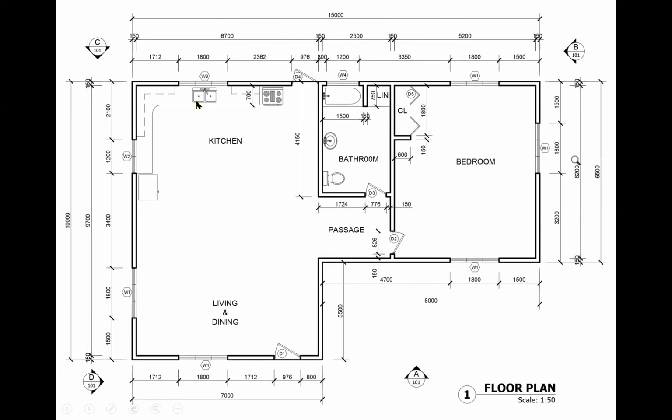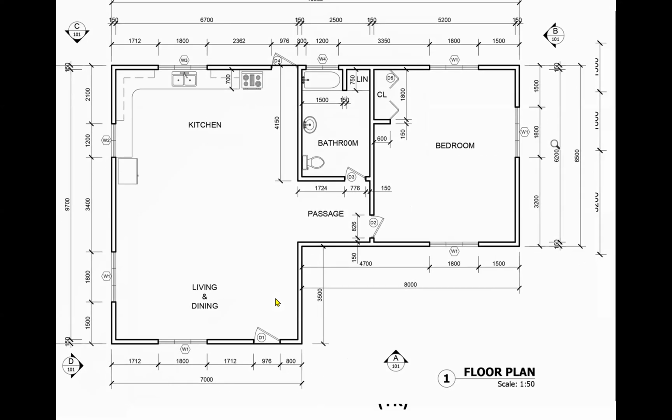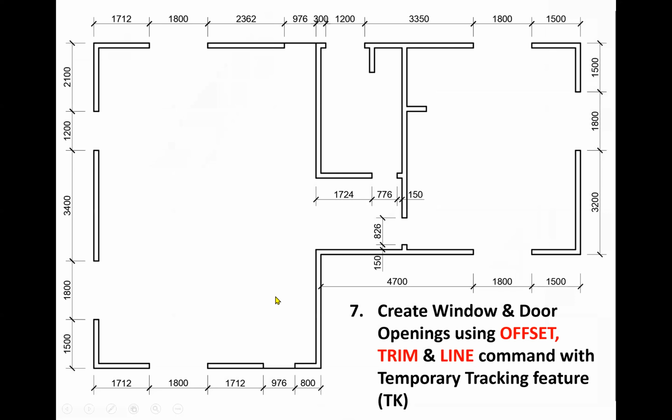All right, so our next move is to start creating openings. So if you notice, there are several openings. We're gonna need openings for doors. We're gonna need openings for windows, right? So I'm gonna go through the steps for the doors first by using the tracking feature again that will help to reinforce. So we are going to be starting with the opening at the front here for the doors.